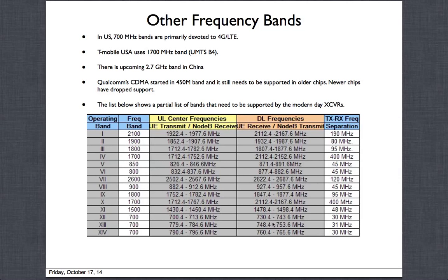They are more like the 5 megahertz LTE mode or lower. Based on all this, many of the bands are also combined to support LTE 20 megahertz in some cases, based on what kind of auctions those carriers won or what kind of tie-ups they have between different cellular carriers. But these are the 700 megahertz bands which are also important.